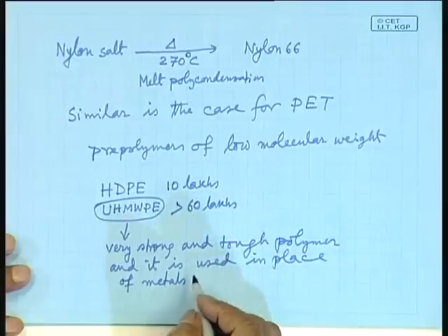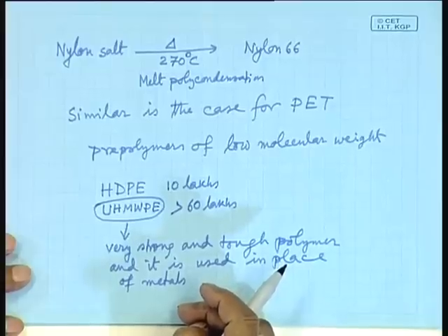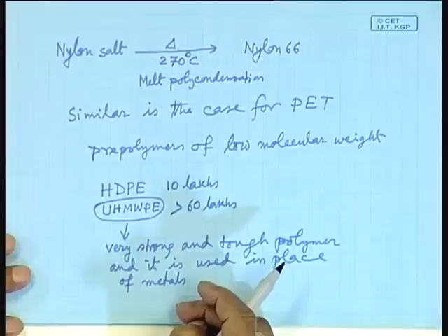Of course, this ultra high molecular weight polymer is processed by sintering, not by conventional polymer processing techniques, polymer processing machineries. Okay. Ultra high molecular weight. So, there you see is an exceptional case, by increasing the molecular weight, you can increase the mechanical properties, mechanical strength, but not always, because the properties level up beyond a molecular weight.